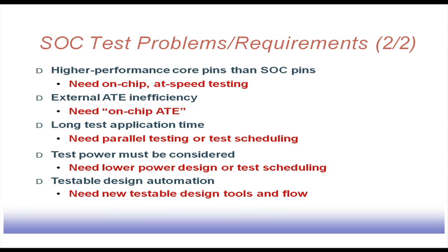Then long test application time. So, what has happened in the SOC design paradigm is that you have so many components to be tested. Now, the IP vendors have provided us with a set of test vectors for each of the cores. Now, if this entire system was designed by a single group or single person, then they could have filtered out the test patterns, or found the test patterns which can test a number of faults in different components.